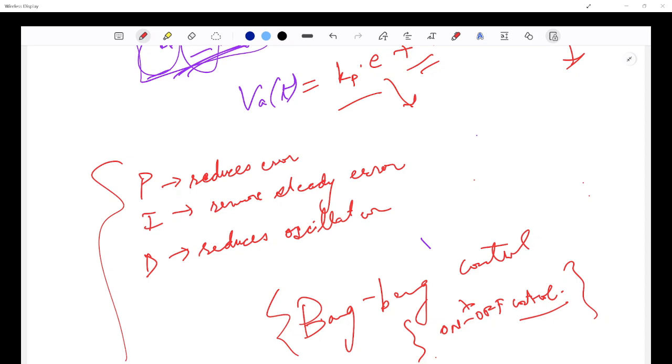For the same reason, fans are also an example of an open loop system. You have a regulator, you choose between 1, 2, 3, 4, 5, and your fan speed changes, but it is not always fixed. Sometimes it might move at 200 rpm, sometimes at a different rpm. There is no one to take the sensor reading and correct it. Even if it is moving at more or less speed, it will move. So it is also an example of open loop control.